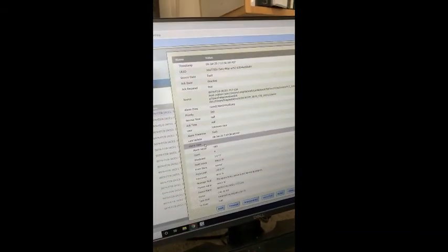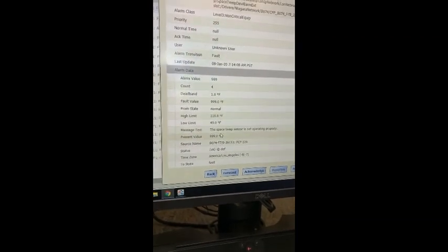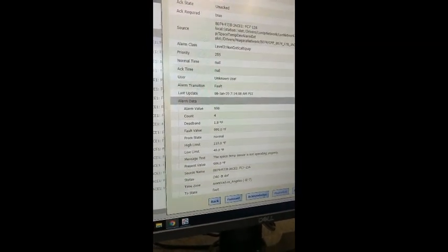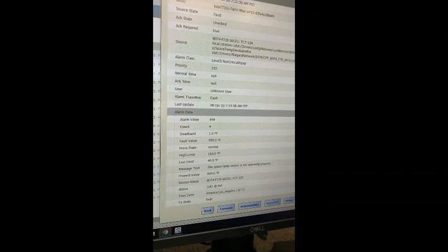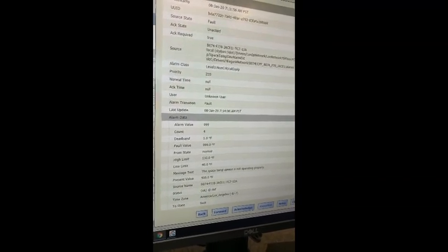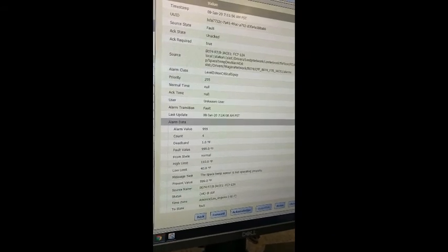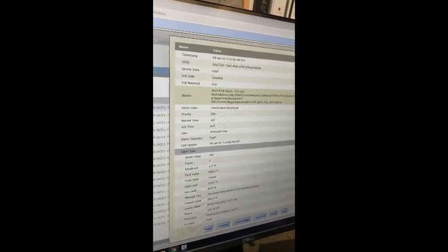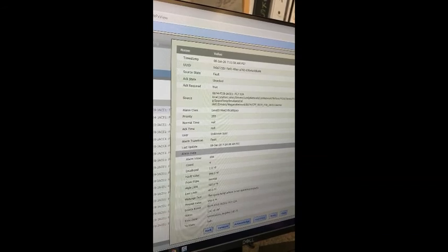The alarm data will give you more information. It'll say like the deadband, the fault value. So this one's saying that the sensor is faulted and it's not reading properly, basically. Yeah. So that'd be the thermostat. That could be that someone took that off. Maybe they're painting the wall or something, or one of the students horsing around, broke it off. So let's actually go and take a look at that. That's building 74, 7th floor, 12A.